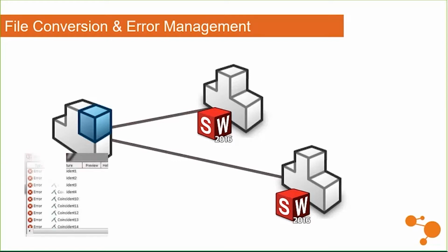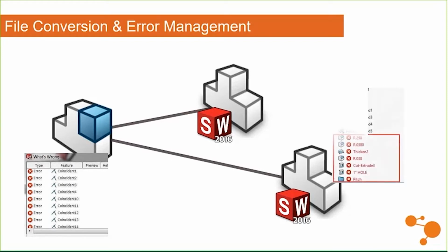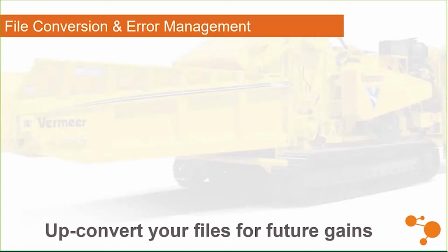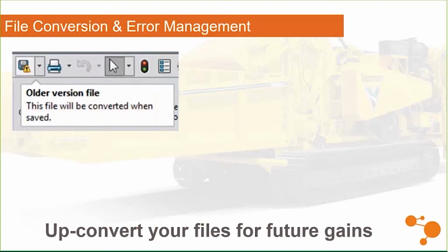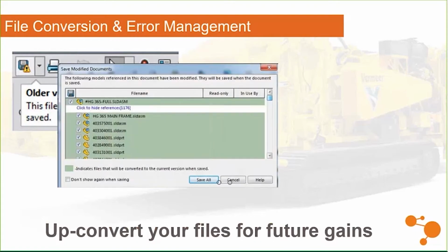To compound that, now maybe I did a pack and go with something and it's got some mate errors in it. Oh, this file over here has got a couple of errors in there. So this is just a recipe for bogging you down. And so it's really tough to show gains and whatnot in here. You're going to see a 10 times gain by cleaning up all your errors? Probably not. But those types of things definitely weigh in on how long it takes to load assemblies in SolidWorks.